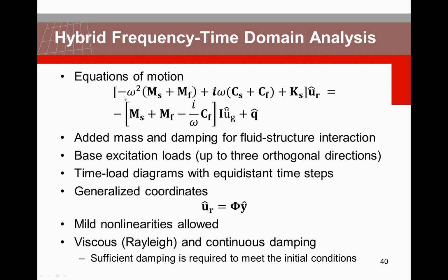And you will also see this occurring in your right hand side. And you see here a special load. This Q load is a so-called pseudo force, which will be taken into account in the frequency domain, and it represents the nonlinear effects which occur in the time domain.